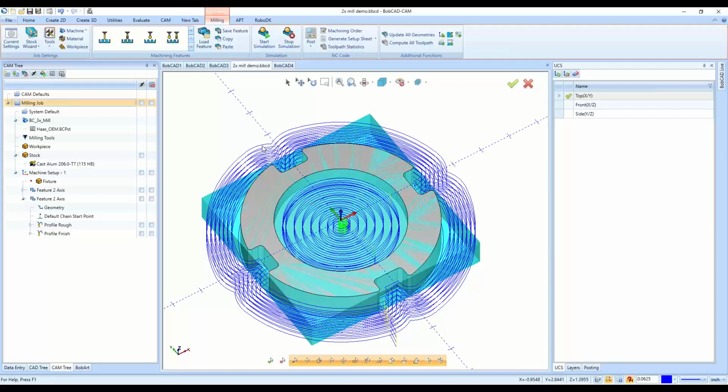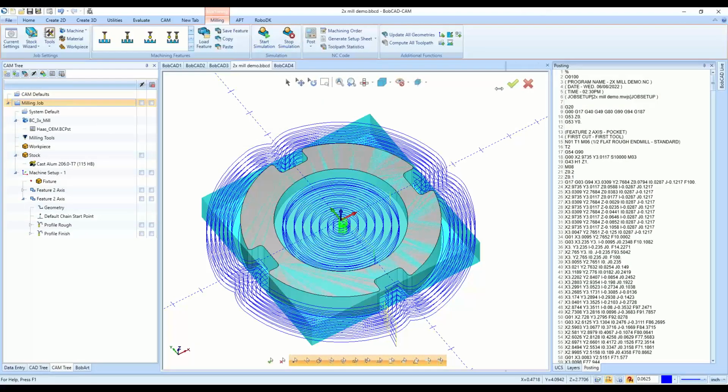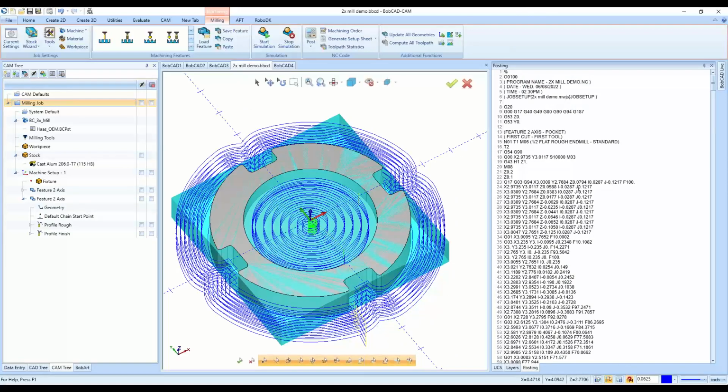Now I think we're finally able to post the G-code. We've simulated. We've seen that the areas here into these tab areas here are cut to size. Everything here is cut to size on the part. So after simulation, stopping simulation, we have post. It will post the G-code here on the right-hand side. And again, this is set up for a Haas controller, this formatting.